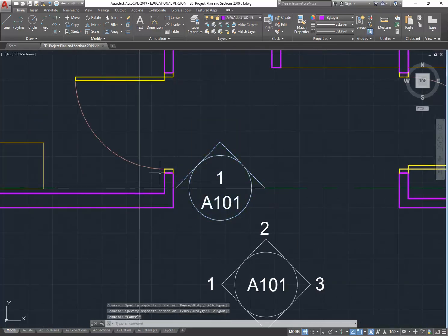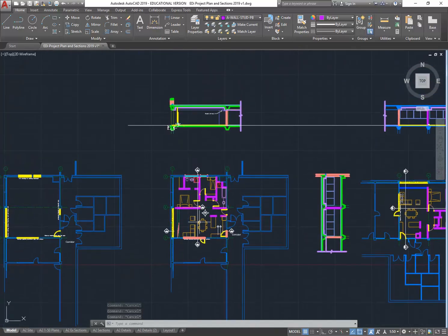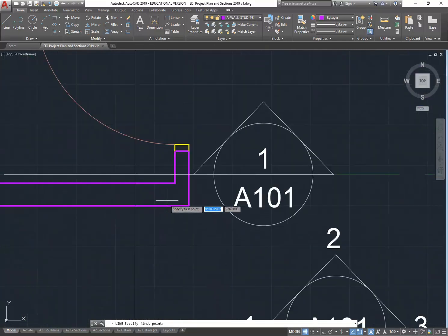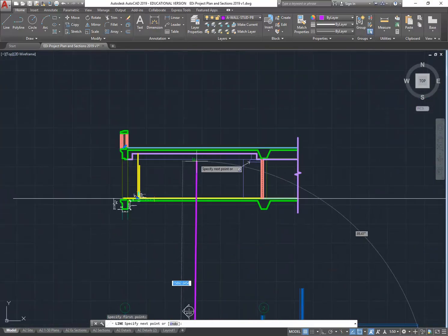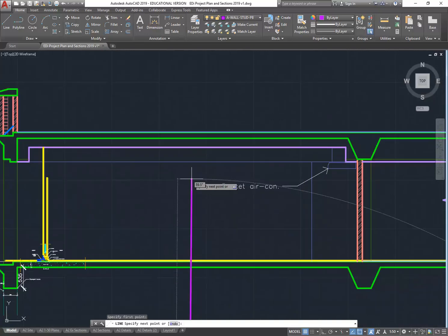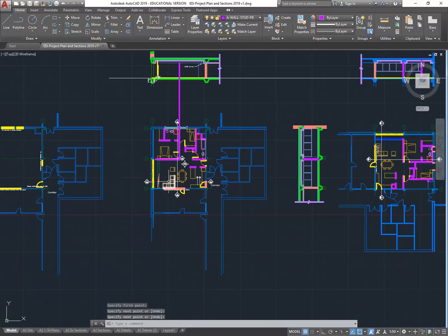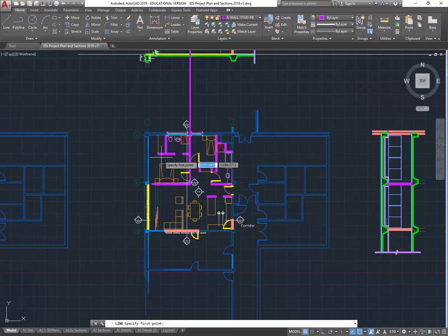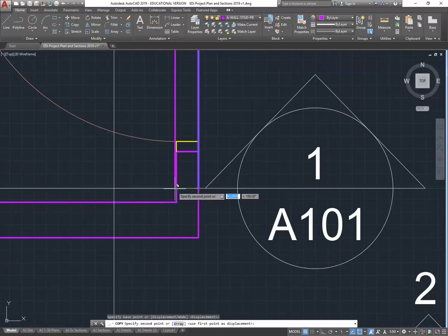So then I will project off the other way, and I've got another section going that way already, so that's what I'll use. And so projecting lines again going this way for my wall, and again that'll give me the starting point for my detail. So remember, we're going to change this to a flat ceiling, so I'm only going to take it up to the line there of this ceiling, and then draw another one on the other side, or alternatively copy the line I have just drawn. It's probably a bit easier.